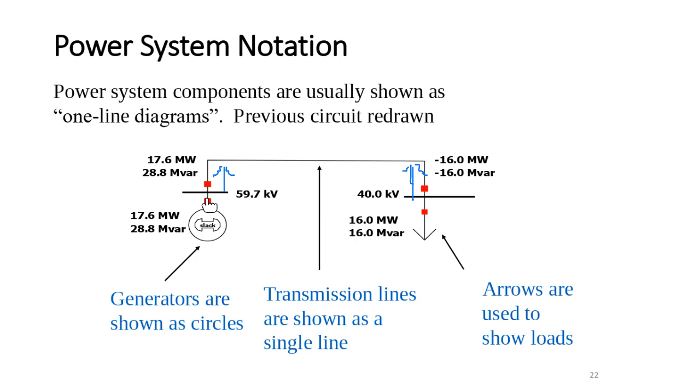You need to write these down, because that's the way we ask you. If the generator delivers reactive power, gives reactive power, the power factor is lagging. Why lagging? Because if the generator delivers reactive power, it means the load is absorbing reactive power. Of course, where will the reactive power go? It will go to the load.